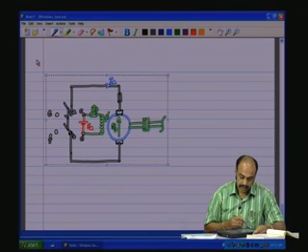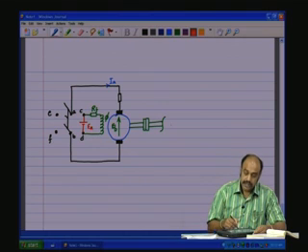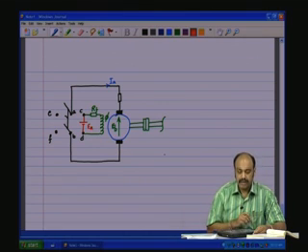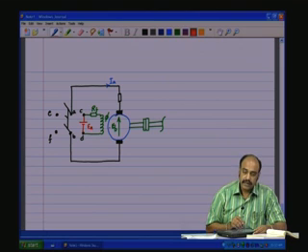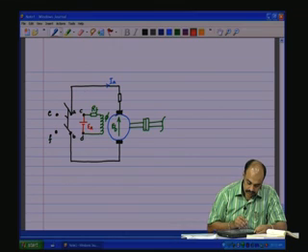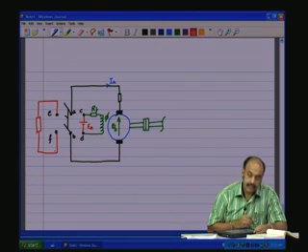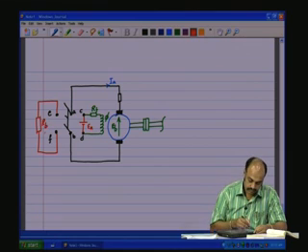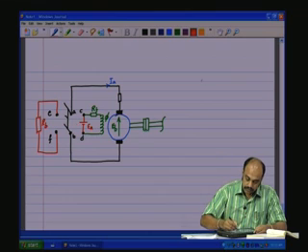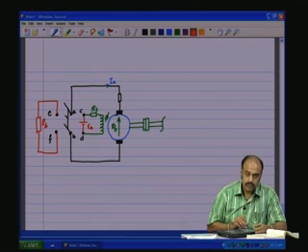In dynamic braking, the energy stored in the inertia of the mechanical domain is going to get reflected as EB. It is a generator. Now, that EB we will try to remove by connecting a resistor here, let us say RB. So, when it is motoring, the switch here is connected to C and D, which means AC is short, BD is short, it is motoring, IA is flowing.